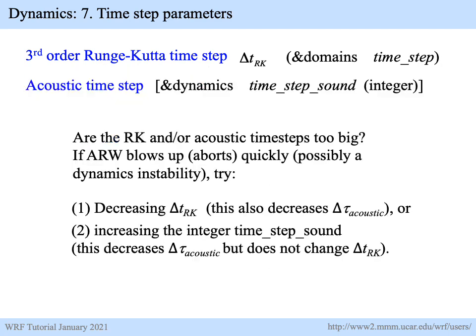So you've set your Runge-Kutta time step, you've set your acoustic time step. If either of those time steps are too big, it is likely that WRF is going to blow up. It will abort quickly because there'll be a floating overflow. If that happens, there are 2 things you should try to diagnose what happened when the model blew up quickly. And quickly means a few to less than 10 time steps. First thing you can do is decrease the Runge-Kutta time step, because this will also decrease the acoustic time step.